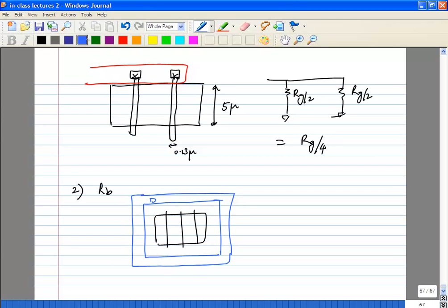It will look like this. This is actually a substrate ring, a ring around the transistor full of substrate contacts, because RF transistors are especially sensitive to substrate effects. You try to make sure it has a very good substrate, because the actual connection to the substrate may be very far away.